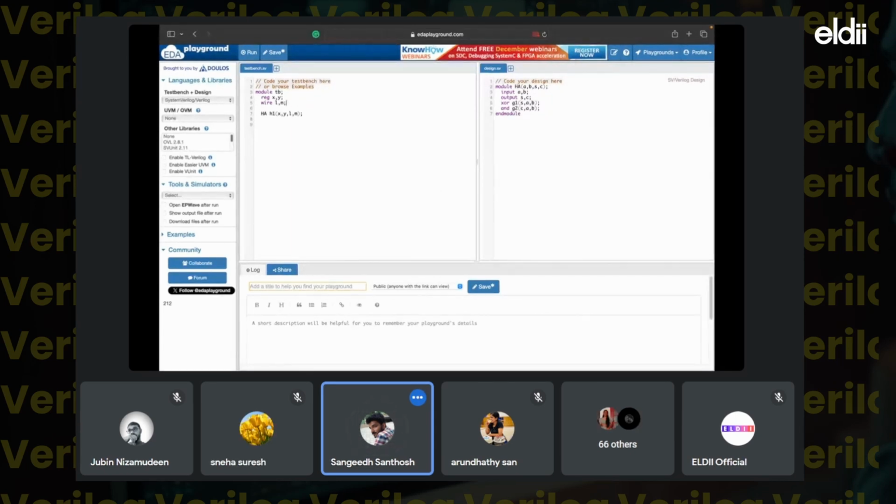Then we need to give input values. Here I have not mentioned any size of x and y, so by default it will take values 0 and 1, and x and z. X is don't care and z is high impedance. Don't go into that deep; we'll just discuss 0 and 1 now. There are two blocks in Verilog: the initial block and the always block. We'll discuss the difference in the coming slides.